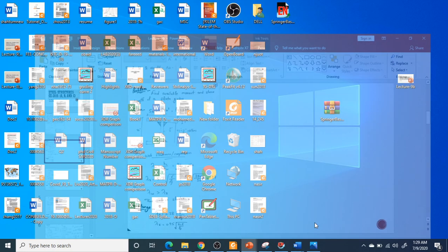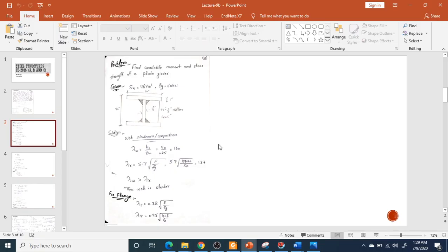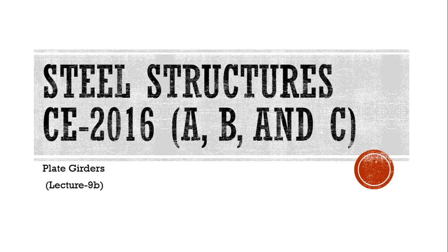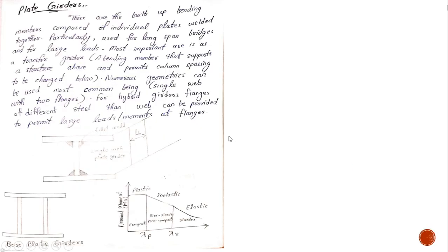This is our second lecture on design of plate girders. Plate girders, as I told you in the previous lectures, are flexure members, and they are built-up members because they are built up on demand. They have long flanges and a very deep web or stem, and they perform the function of the deck of any bridge, of mega bridges.